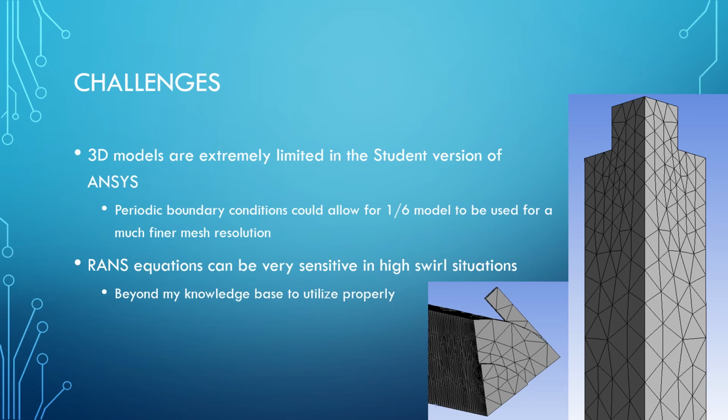Some of the challenges here were just that 3D models are pretty limited as far as how you can utilize them with the student version of ANSYS. You only get 500,000 cells. I ended up not getting too close to that and getting good results, but I do think I could get better results and trust my results a little more if I could confidently get more cells.